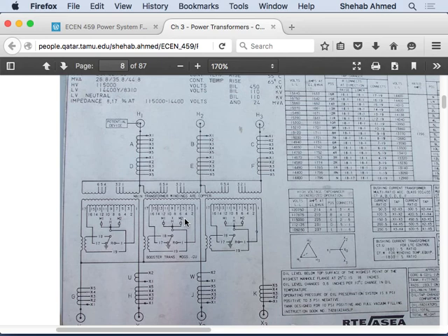And anytime you are consuming power, your current is flowing from the generators through the transmission lines to the loads. You have voltage drops around the system, right? If one area is consuming more power at a certain time, maybe the voltage drop on the way to that area is higher than other areas. So there's a voltage profile in the system. It changes all the time.